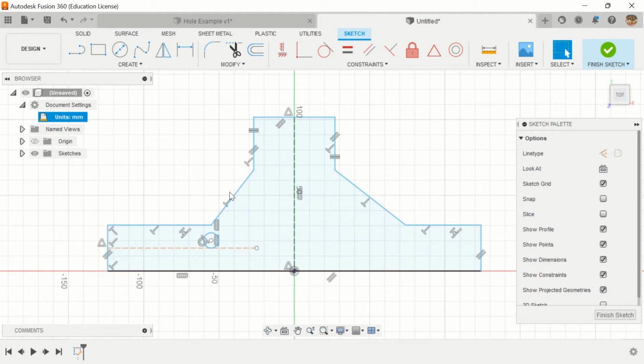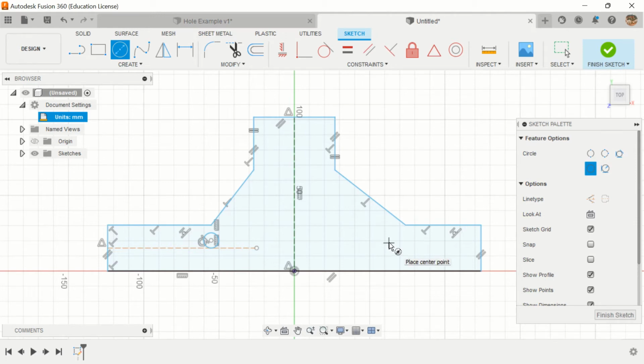Now this is where I did not like how the directions in PLTW tell you to do this. We'll see how it goes, but it says draw another circle in a similar location on the other side. Then constrain the second circle to be symmetric to the first using the construction lines.